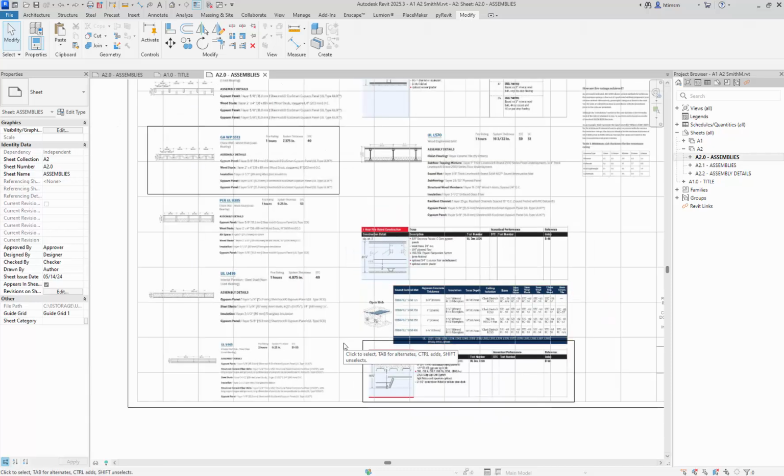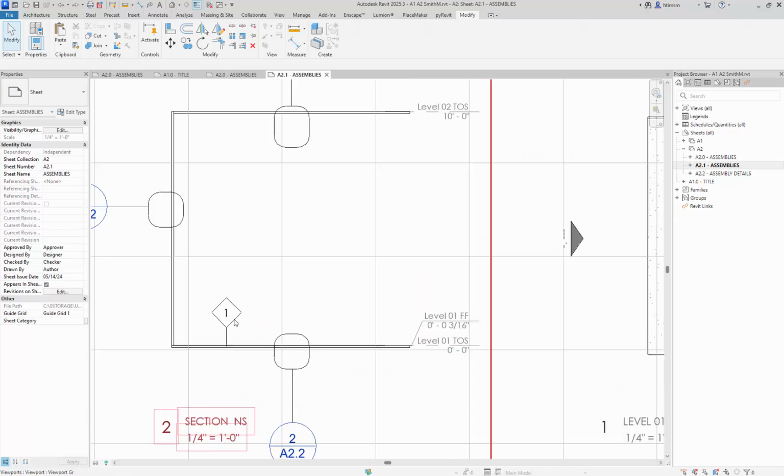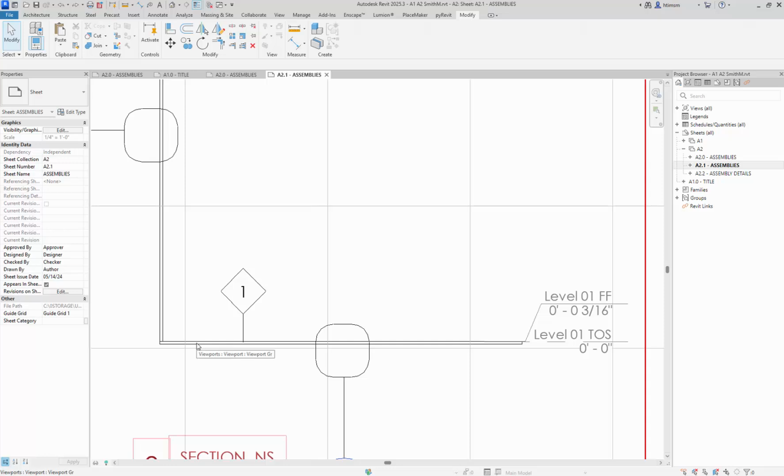Like the base, we're just going to say it is a 6-inch slab. It's not going to have a basement below it, so it'll be pretty straightforward. So we'll go ahead and start with that. If I go to my 2.1 assemblies file, you should have something that looks like this, these little inch things. And the first thing I want to do is create the slab that's below the floor and then adjust the existing floor to the correct depth.